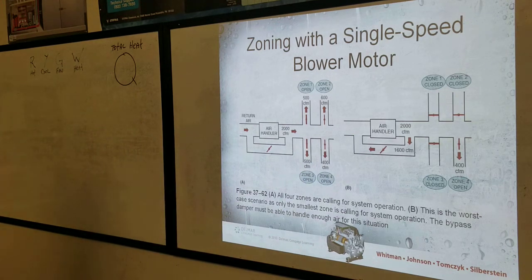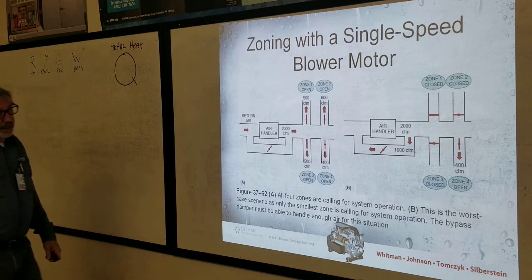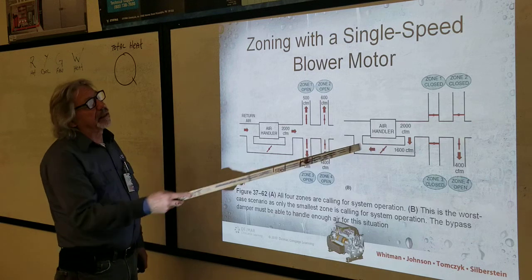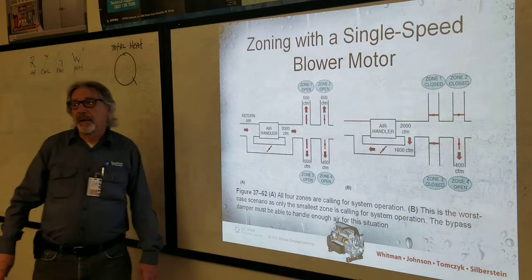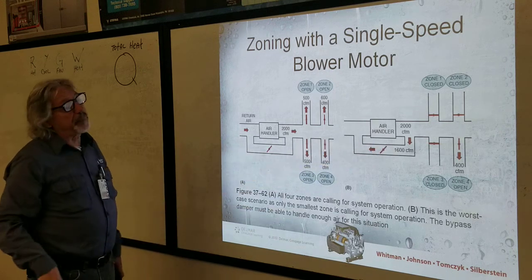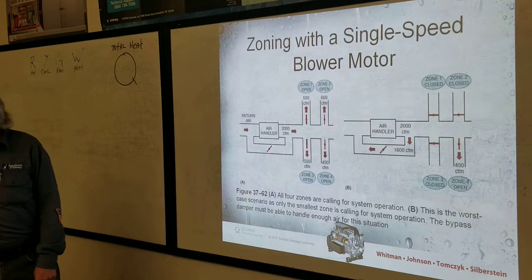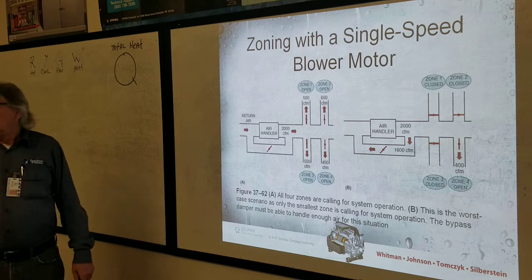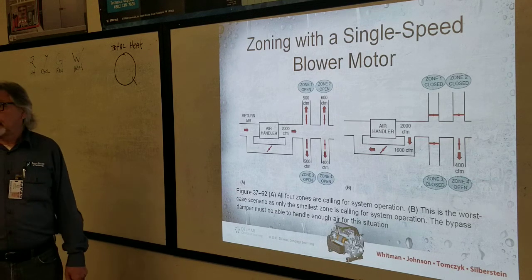So unless that system has a variable speed blower, if it's got a single speed blower, it's going to have a backflow or a bypass damper somewhere. Exciting.